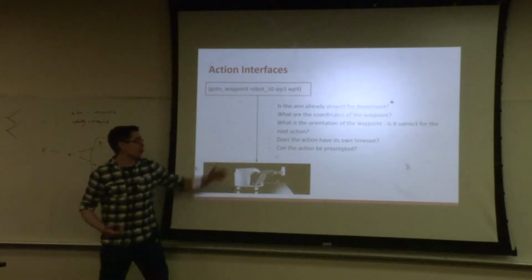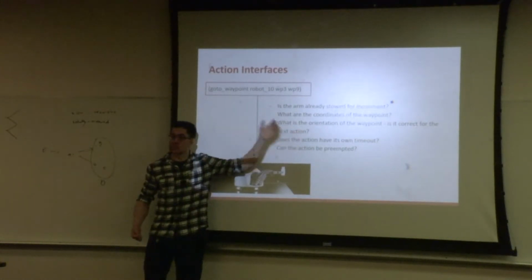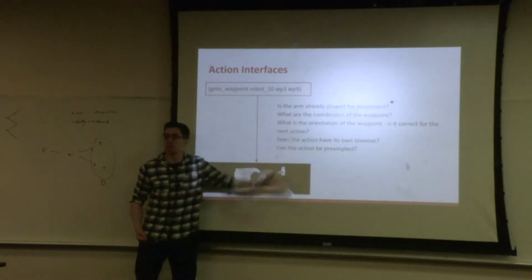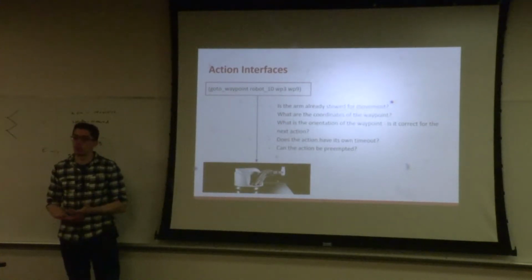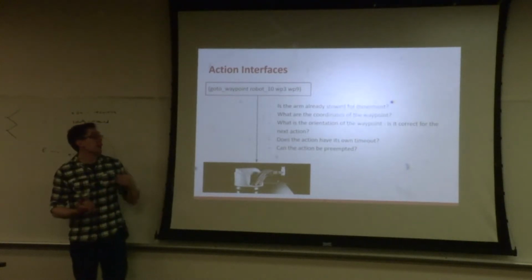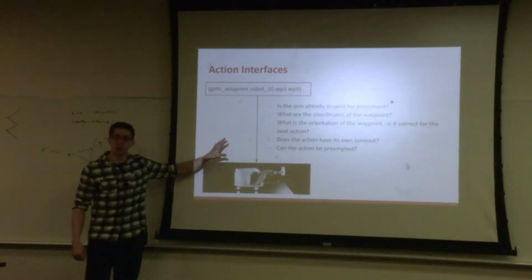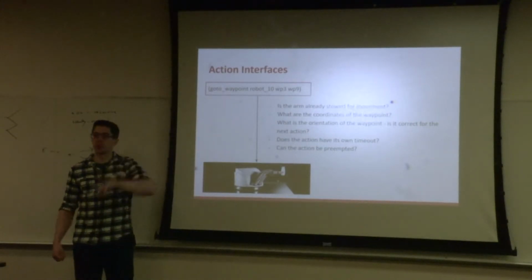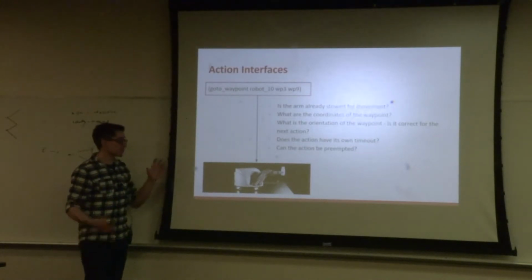But then again, why not just model the exact coordinates of the robot and the orientation of the robot directly in the PDDL? Why not is because then you'll never be able to solve the problem. You have to make some kind of abstraction. You have to make it simpler. And this is where you pay for making it simpler, because when it's time to actually execute those actions, you have to make them complex again. And the way in which you make them complex can be tricky.